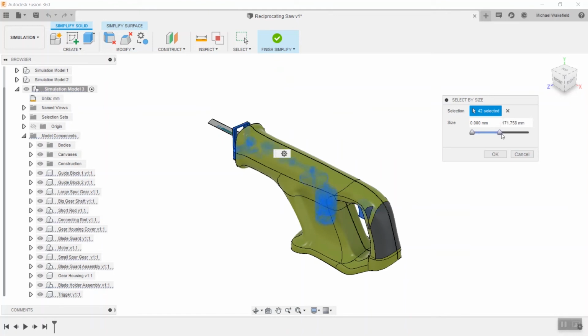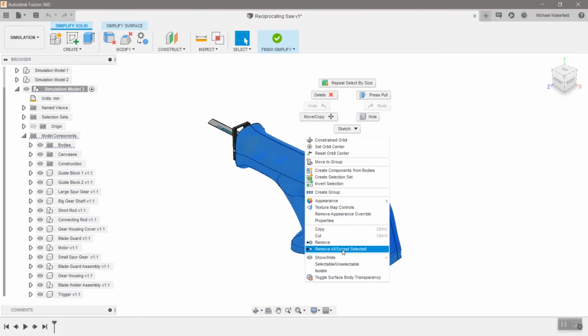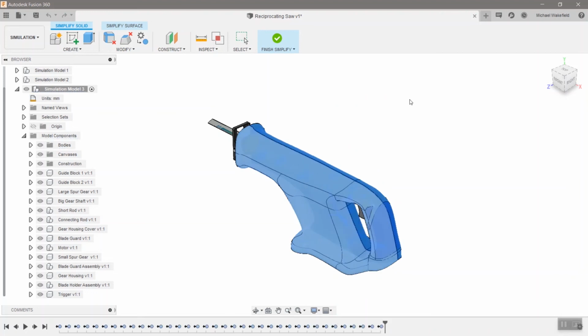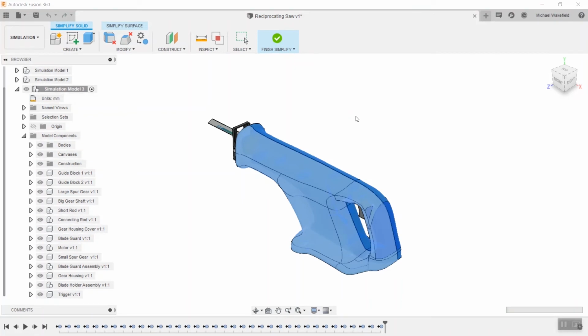And so I can go in here and use these sliders, and I selected just about all the parts because what I really want is just one half of this plastic injection molded part on the outside. So I picked the three largest parts. To be honest, I didn't know what the third part was, so I then hid one side of the handle, and there's a surface under there that was originally used for modeling this part. So I just selected that, and I should be able to delete that later.